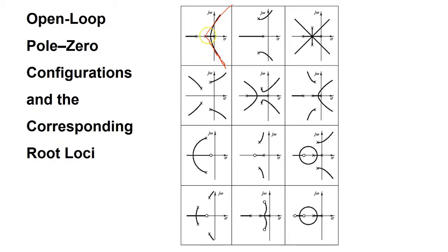They hit right at point -1. And let me draw the third asymptote as well for you. So these are the three asymptotes in this graph. But at what point does the actual graph, this black curve here, get off from the real axis? Here, this guy here, if you look at it, this guy is the breakaway point.